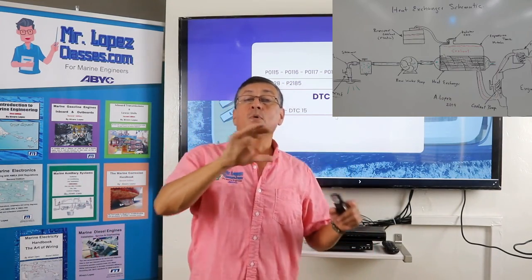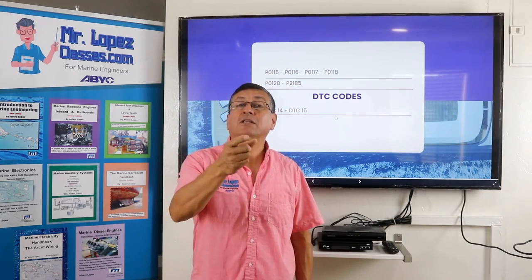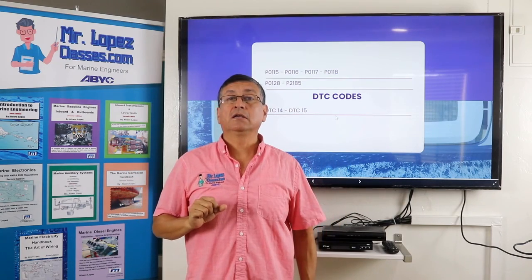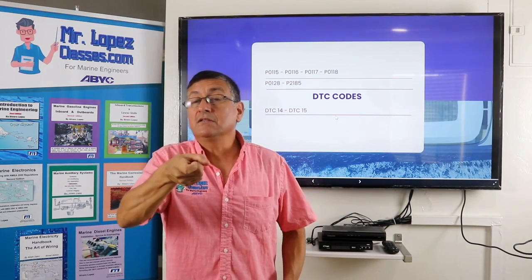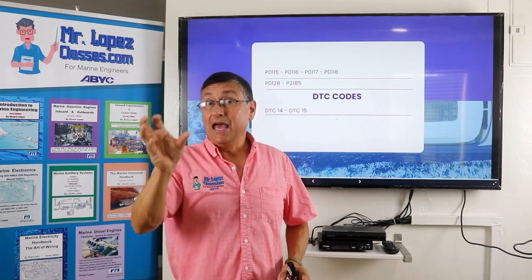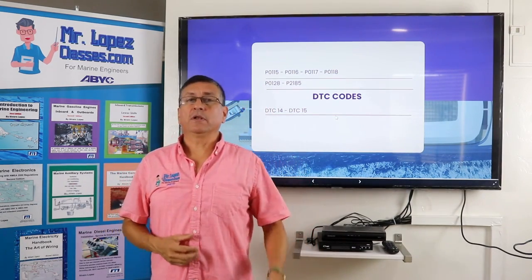You need to analyze both cases and verify where the problem of temperature is. For that reason, the temperature gun is very important. You need to keep the temperature gun in your pocket to analyze which cylinder has high temperature, what part of the engine, the elbow of the exhaust is critical, and analyze where the problem is.